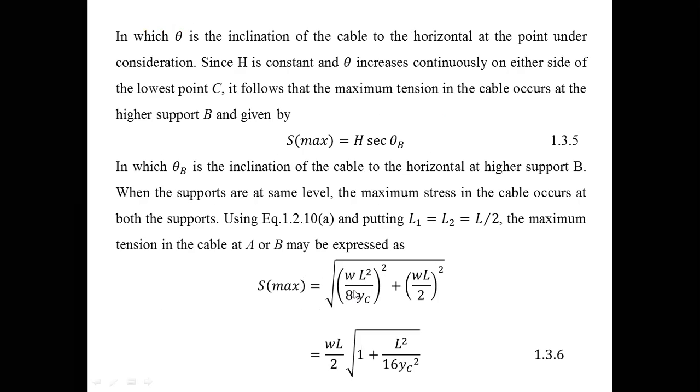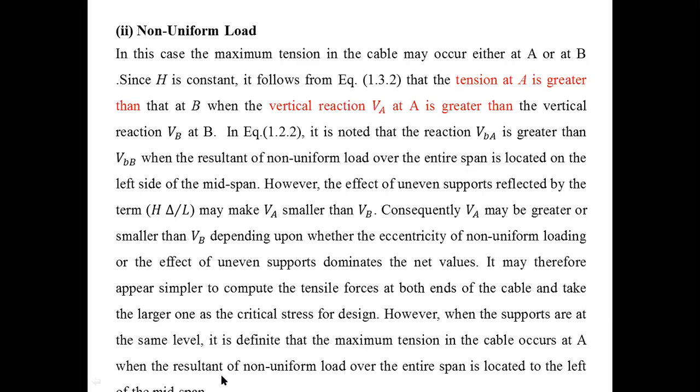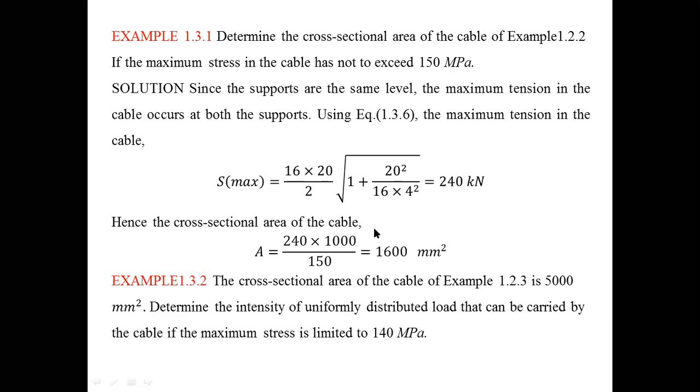Bending moment is WL square by 8. That divided by YC will give the H, whole square plus the maximum vertical reaction WL by 2, squared. From this equation you get this. So use this equation and find the maximum tension in the cable, which is 240.